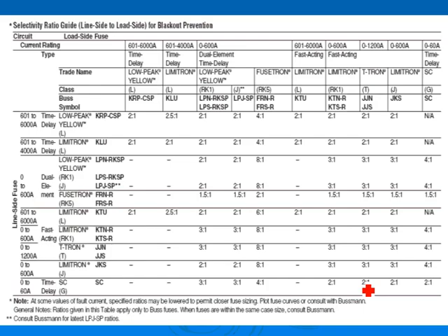Here's a chart. If you don't have the fancy curves that Chad has, here's the rule that we use, guys, as engineers when we coordinate. For fuses, rule of thumb, if your feeder is half of your main, you have good coordination for fuses, typically. What does that mean? You have a fuse disconnect right here on the main, and you feed that panel, and you came out of here.